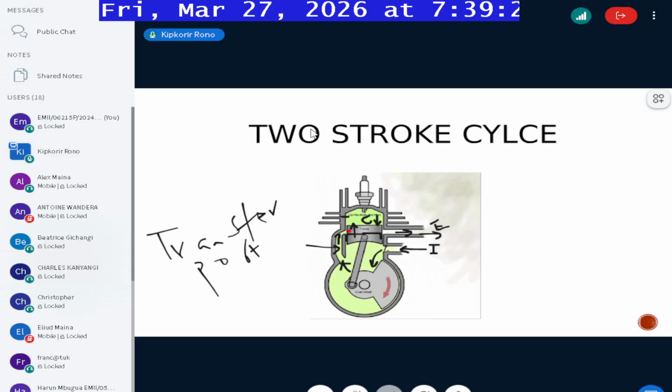They'll rush upwards because, remember, as the gases exit, they leave the combustion chamber with very little pressure. Because of the pressure differential created with the air and fuel that had come in from the previous stroke, they will rush upwards. As they rush upwards, the piston will come and completely close the intake port, so there'll be no intake at that point.